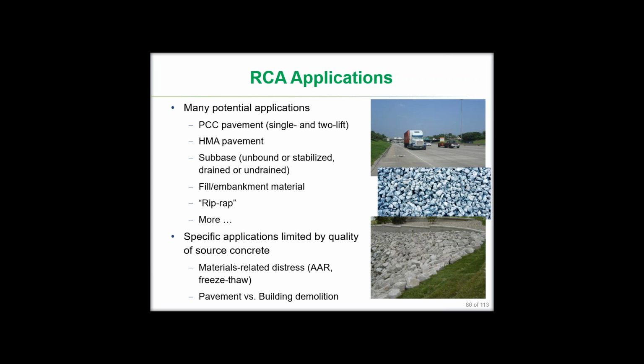It can be used back in hot mix asphalt, as Hassan mentioned earlier and Imad mentioned. It tends to have a little higher absorption, so it's a little more asphalt cost there, but it has been done successfully in hot mix and warm mix asphalt. The most common application, far and away, is into unbound base layers, occasionally stabilized base layers, and these layers may be drained or undrained. There are some concerns when you use a drained unbound material, and we'll talk about those here in a little bit.